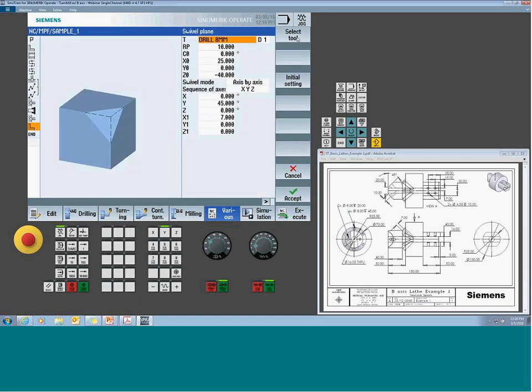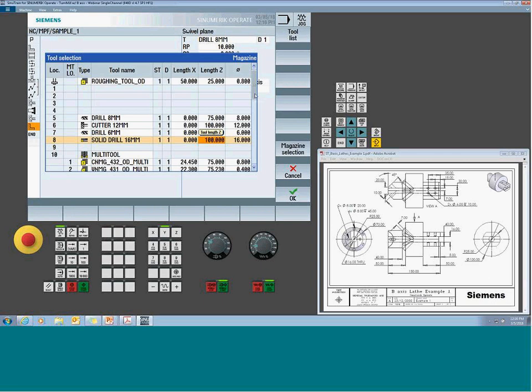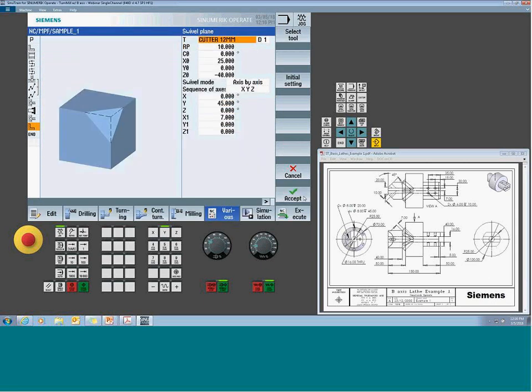We're using swivel plane. Now, here, I'm probably going to want to grab the tool that I'm going to be using. We're going to be using a 12 millimeter tool to mill this surface. So I'll let it do a tool change now. We can track the plane wherever I want to back up to when I'm done by orientating my C. I may not know this in your first surface, so check whether everything seems to be aligned the way I want it. If not, you can clock it. So it's sliding my X up 10. My Z wasn't changing. So that was putting me right at this corner, right at the pivot point. A positive 45-degree rotation.